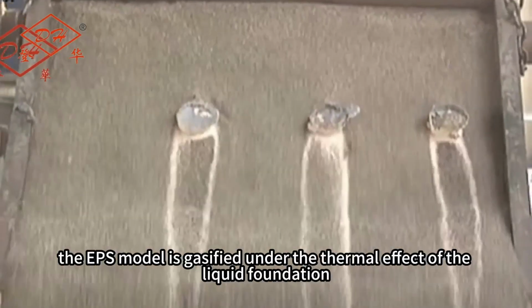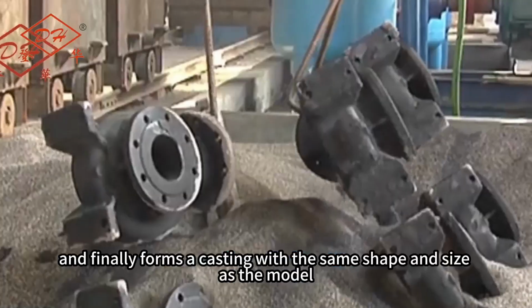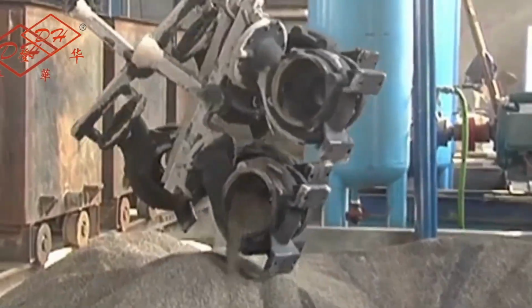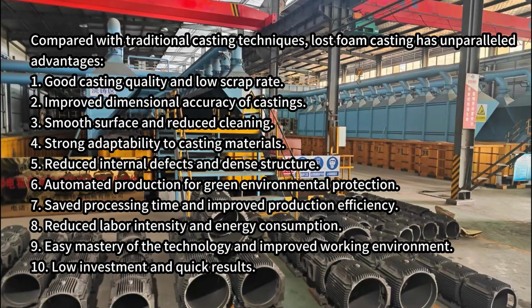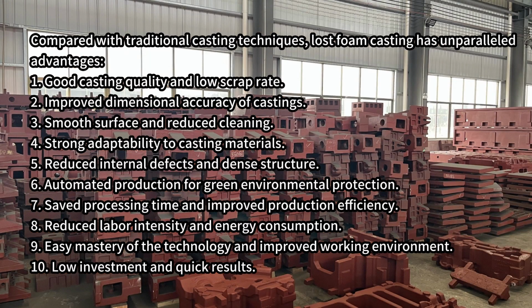During pouring, the EPS model is gasified under the thermal effect of the liquid metal, and finally forms a casting with the same shape and size as the model. Compared with traditional casting techniques, lost foam casting has unparalleled advantages. First, good casting quality and low scrap rate. Second, improved dimensional accuracy of castings. Third, smooth surface and reduced cleaning.